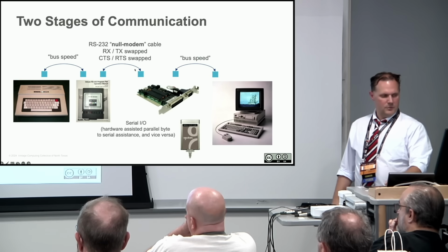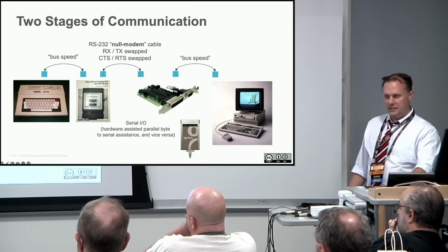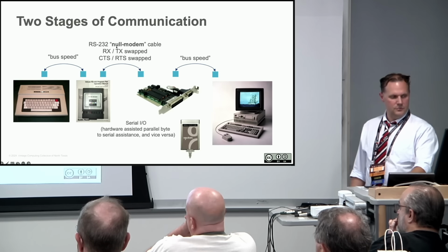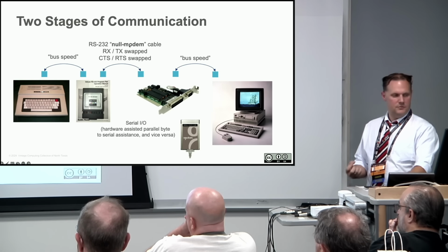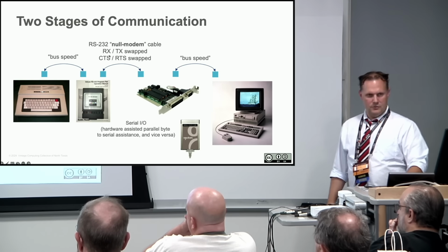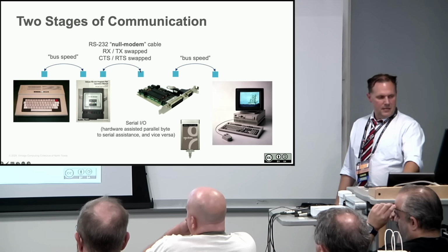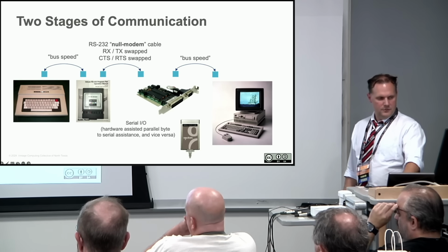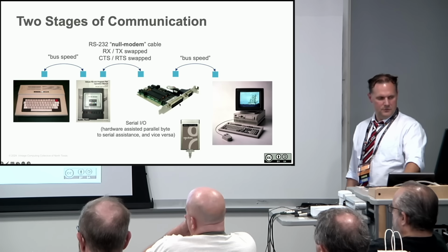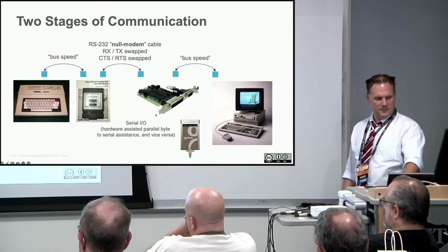Or these days, if you want to talk to something else, you can talk to basically anything else that also has RS-232. Use a null modem, basically take out the modem, use a null modem cable, and all they do is swap these two lines, the flow control lines and the transmit and receive, and you can talk to another RS-232 system. You know, PS2. I've talked to my modern PCs.